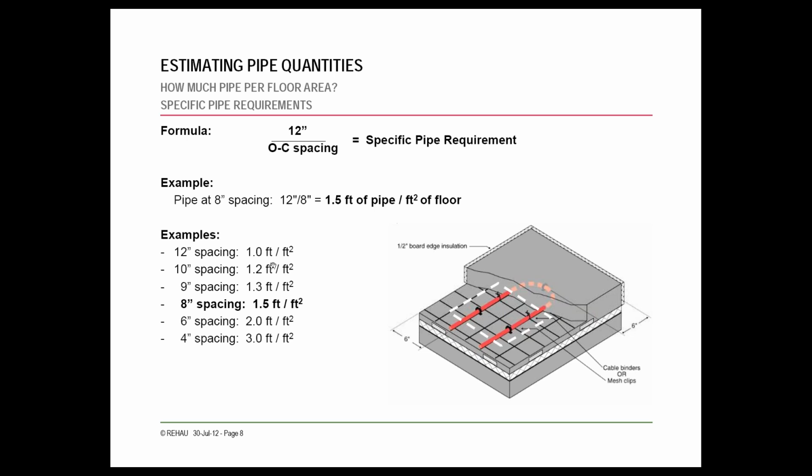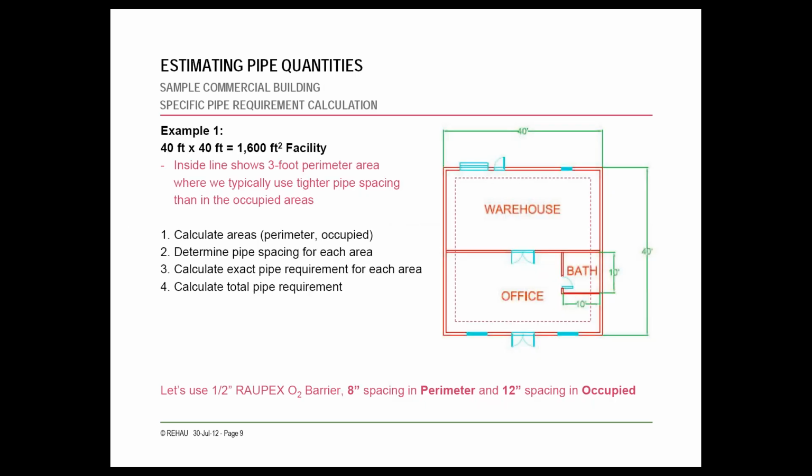The common spacing that we see is almost always 12-inch spacing. If you're going to be doing snow melting, it's more commonly around 9 inches. And we see 6-inch occasionally. That's usually with cooling, though. As I mentioned, you can go a little tighter along the perimeter. So you may want to tighten the spacing to 6 or 8 inches for 1 or 2 lines right by the perimeter, and then go back to 12-inch spacing. That's certainly something you can accommodate as well.